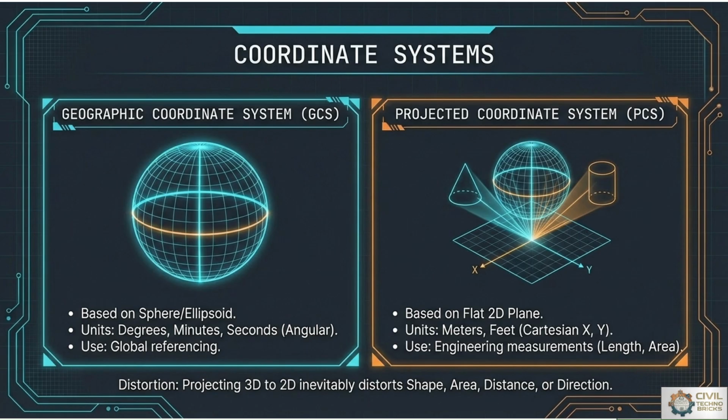So, projection from 3D Earth to 2D maps causes distortion in shape, area, distance, direction, etc. So we have to select an appropriate coordinate system, which is important for GIS analysis and remote sensing applications. Our main aim is to select the correct coordinate system which will be more useful for getting the outcome on the basis of the selected objective in the project.